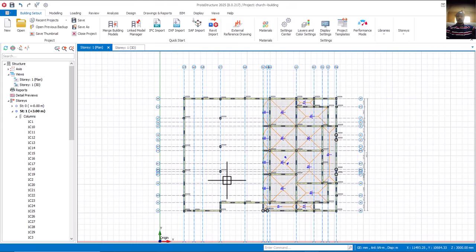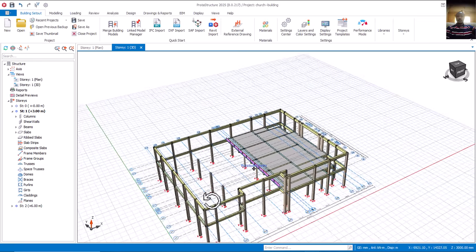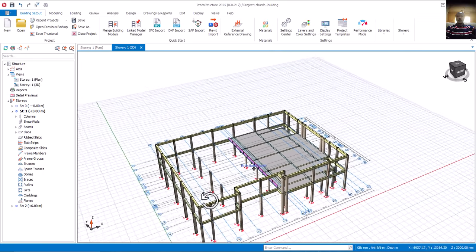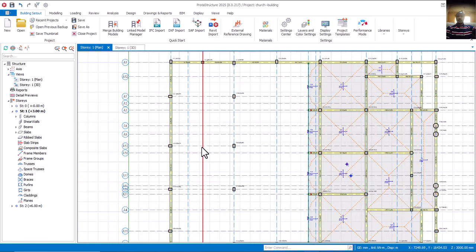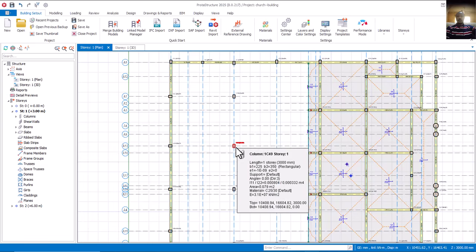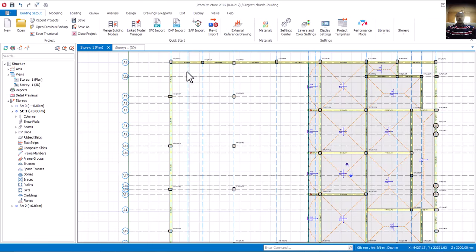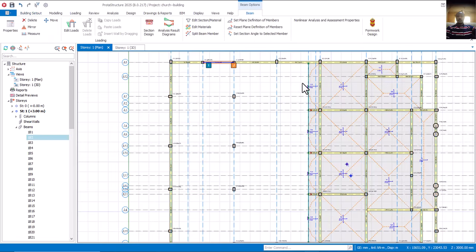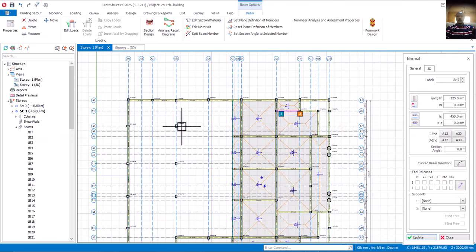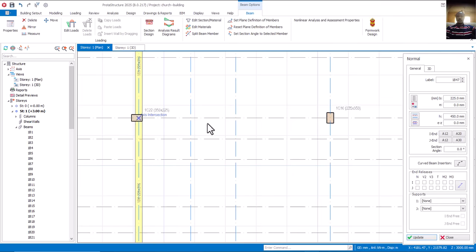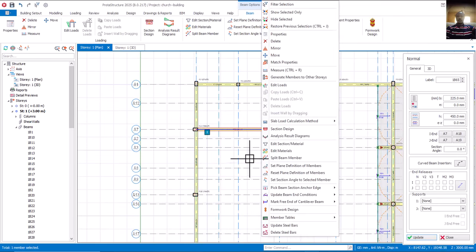Okay, that's fine. So having done this one now, I'm going to be having my wall along this part. So I'll come here now along this part. So this one connects to this one. This is a beam here. This is a beam here. So I'm going to pick my beam property. Let me confirm this. Let me use this 450. From this point to this point. Then escape once.